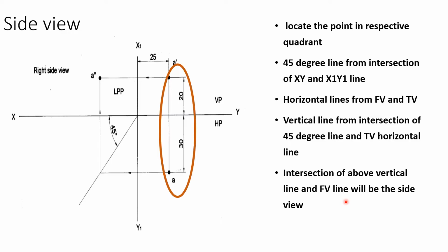Okay, and one more important thing in the points is they will give a shortest distance. Okay, shortest distance is nothing but this diagonal. Okay, where exactly we're going to cut here, or maybe this point. So that means they will provide this length and you need to cut an arc in order to get the length. So they will not specify this one. So at that time you can use an arc by center point method in order to get the side view of that. Okay, so that's for the 8 marks.